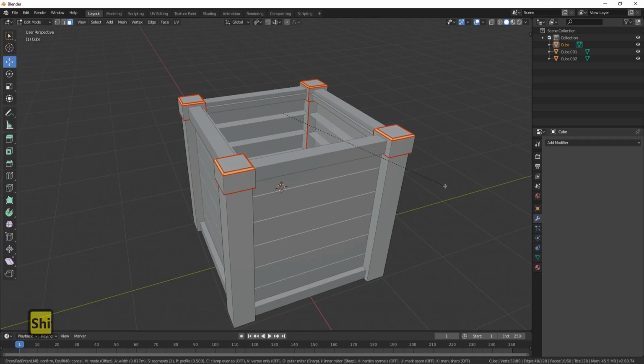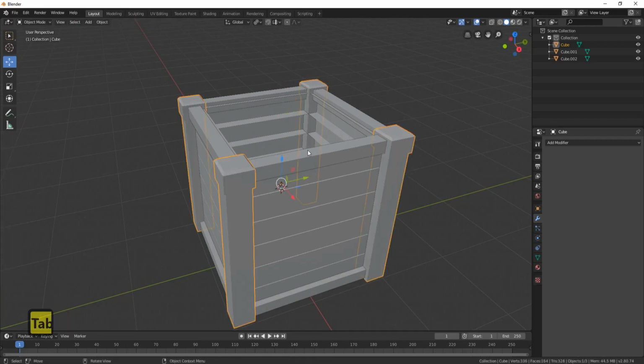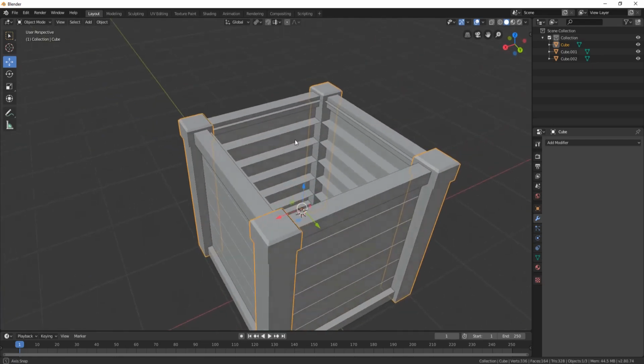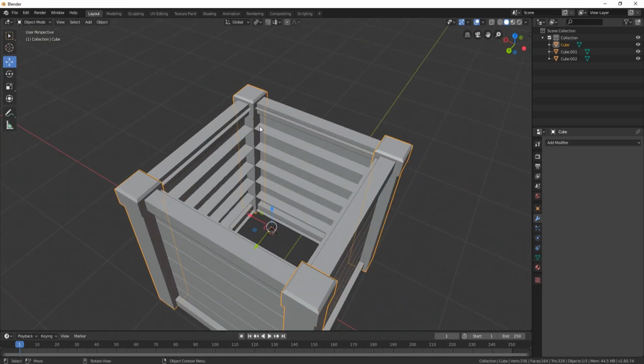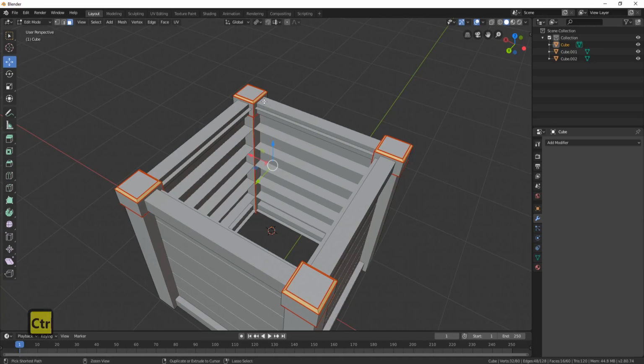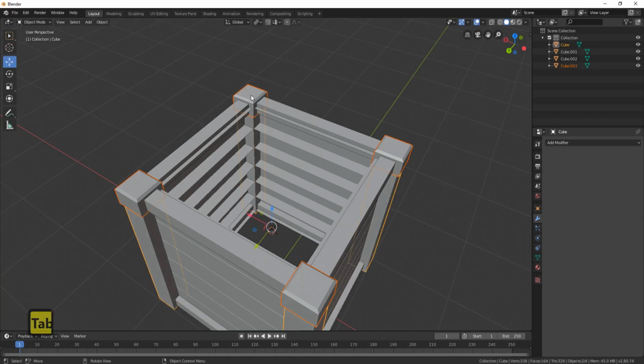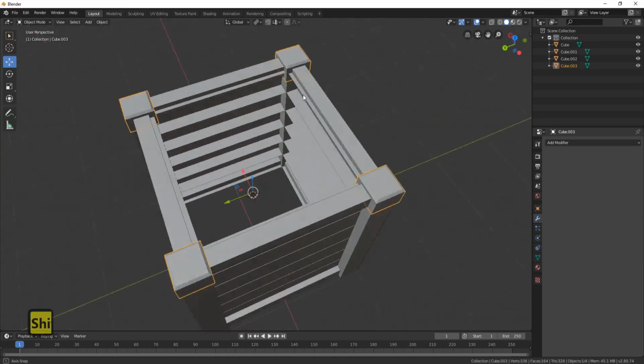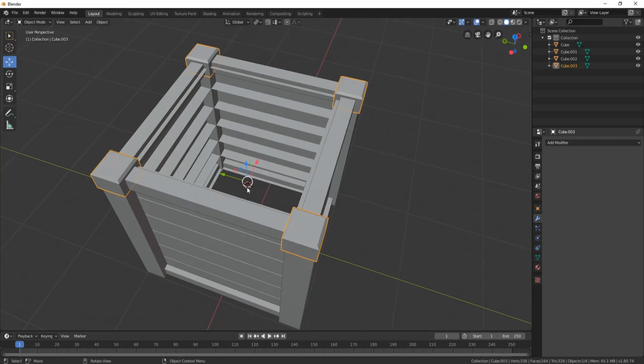And you can hold the shift button down and that can slow down how fast you're pulling those out. So just make them until you're happy with them, until they look crate-like, let's say. Now press tab, and what we're going to do now is press Ctrl plus, and you're going to grab all those and split them off. So P, selection, tab, click them again, and now we need to set the origin again to this cursor here. So right click, set origin to 3D cursor.